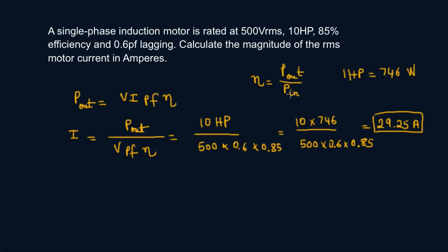Typically, motors are not even that good. I don't know if I've ever seen a motor that's like 85%. That's a pretty good motor out there. Typically, it's between 60, 70, or even 50% efficient. So this is a formula to remember. Essentially, convert your horsepower into watts and solve your problem. I've changed the values a little bit, but you get the point.